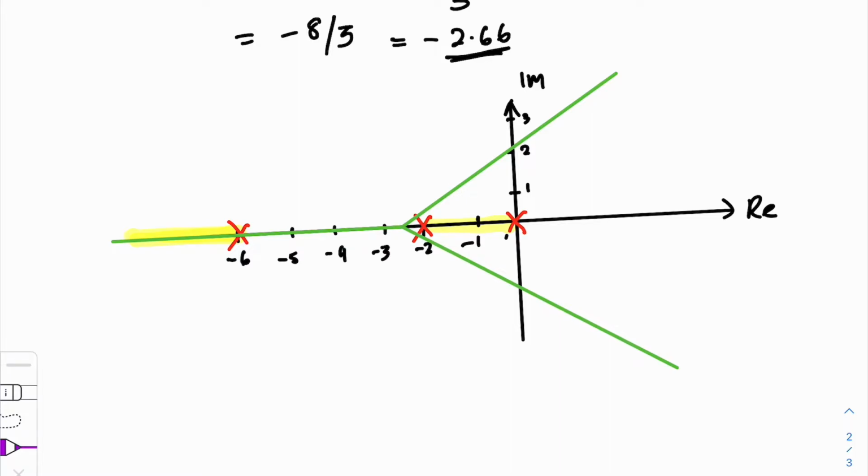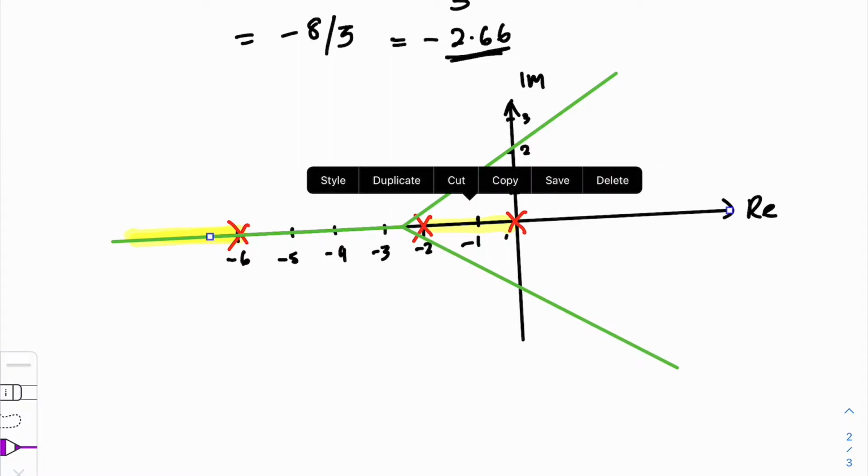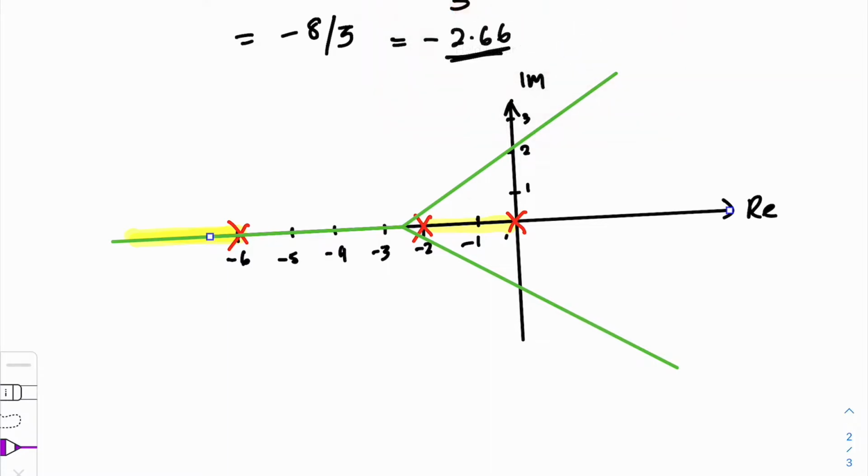Then we can tell from looking at our poles and the region of our locus that our locus will be within that. Between the two poles, there will be one locus going towards each other. There are two loci that will go from that point to that point and meet each other. They will not necessarily meet in the middle. We're going to find out the location of that breakaway point. They will meet each other, and then they will leave each other, because these are two poles.